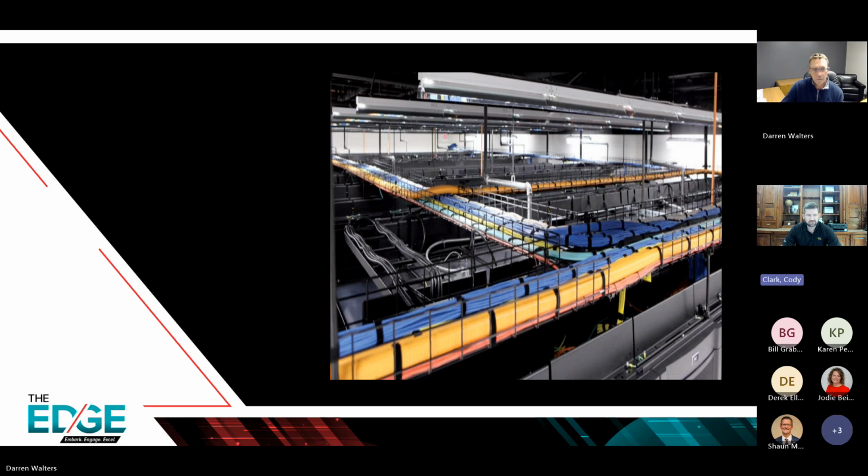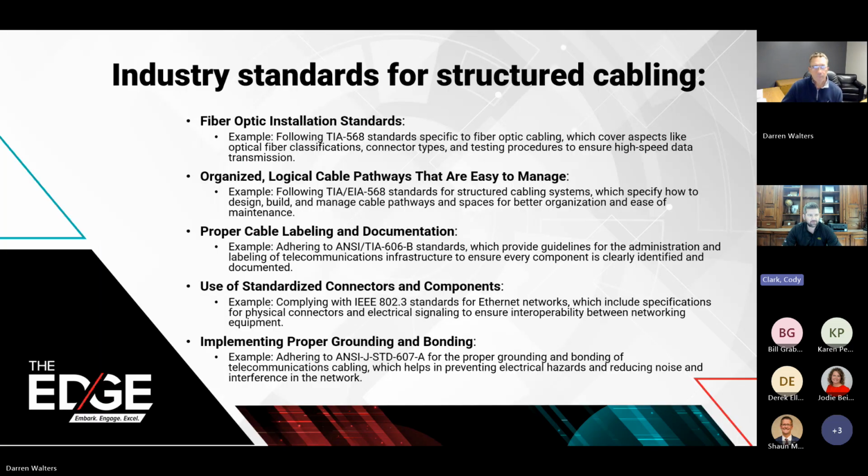Some industry standards for structured cabling: fiber optic installation standards, TIA 568. Important for this would be your testing. This is going to run you through how you should properly test your fiber optic cabling and make sure that it's working properly. Organized, logical pathways are easy to manage.